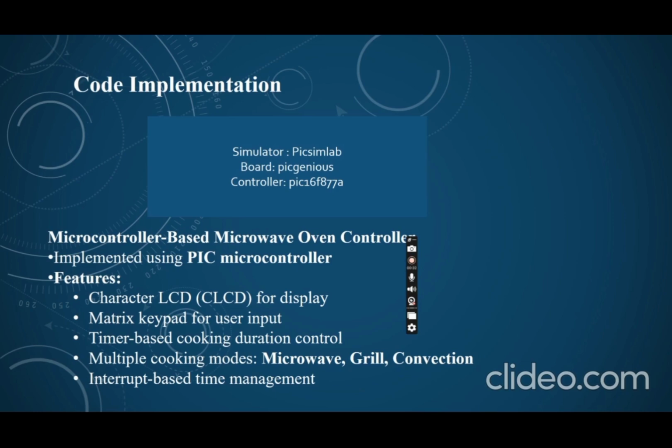The matrix keypad handles input from a 4 by 3 matrix keypad, allowing user interaction with the microwave oven. It configures the row pins as outputs and column pins as inputs, enabling keypad scanning. It scans the keypad and returns the key pressed. The mode parameter determines whether the function returns immediately or waits for a key press.